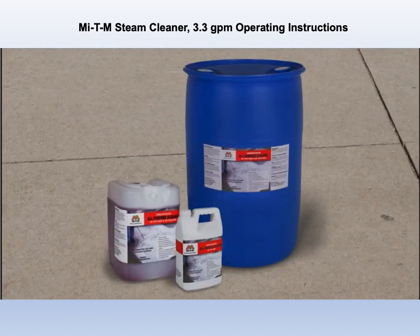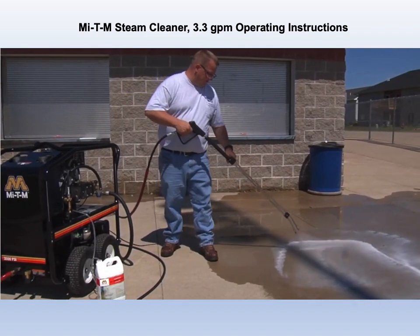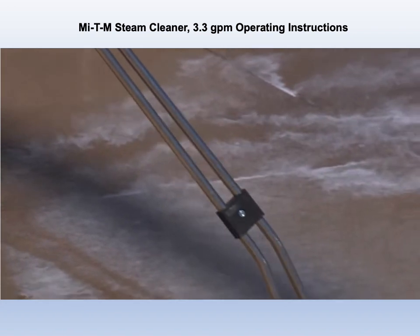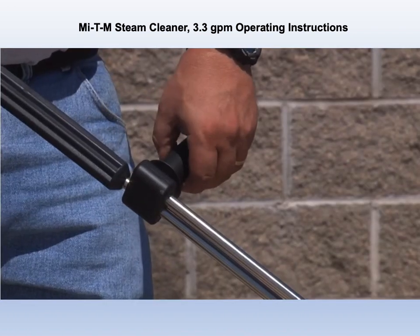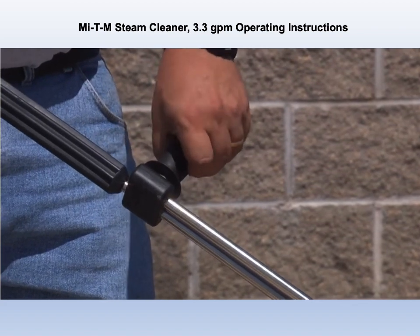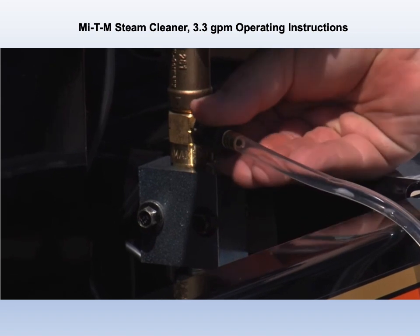Mighty M detergent is specifically designed to break down dirt, grease, and oils for more cleaning power than water alone. Plus, Mighty M detergent is environmentally friendly. When you are done applying detergent, turn the dual lance wand counterclockwise until closed. Close the detergent valve and rinse the surface thoroughly.